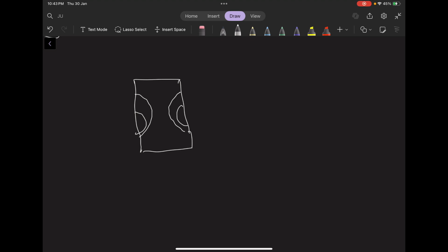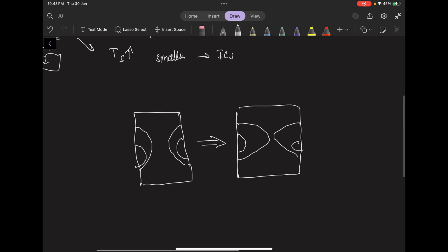And what happens is, after a certain voltage, these two channels basically merge with each other towards the upper half, and this causes a pinch off of the drain to source current that we were getting over here.